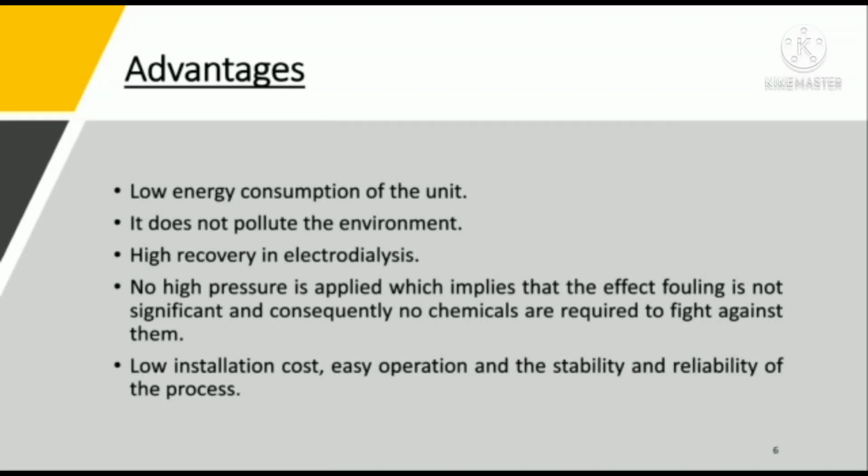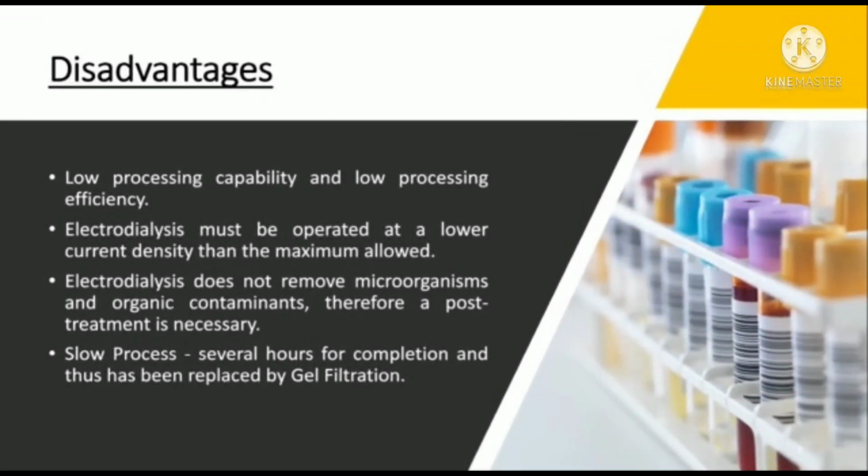On the other hand, talking about the benefits of electrodialysis, its high recovery, especially in the water recovery. Another advantage is the fact that high pressure is not applied, which implies that the effect of fouling is not significant and consequently no chemicals are required to fight against them, which leads to a higher recovery and to a long membrane life. Last but not the least, there is low installation cost, easy and cheap operation, and the process is stable and reliable. And now, moving forward, let us look into some of its limitations.